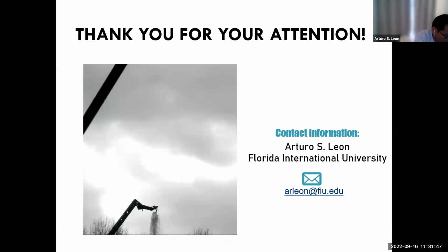Yes. So first, the SWMM model is validated and calibrated using actual measurements in the system. So we use dry flows and wet flows for validating the SWMM model. And second, the cities have actual data, so we can use that for prediction and validation. So actually, we are in the process now. Right now, what we are trying to do is simulate some historical overflows, so we can compare when the overflows happen and if that matches with the model. So we're in the process of that right now.